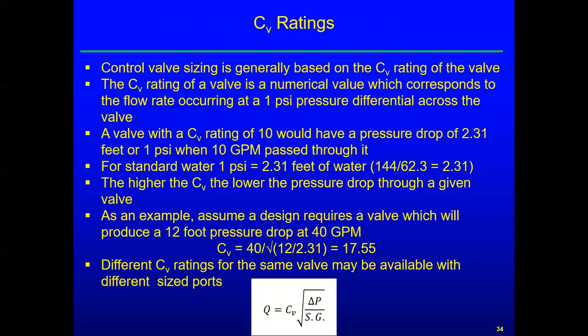Now, if you had different size pipe and different size valves, you would have to include that geometry factor to do it correctly. These slides don't get into that. These slides are more fundamental than that, but that's why I gave you that assignment, so that you would realize that this is a stripped down version of this valve equation.